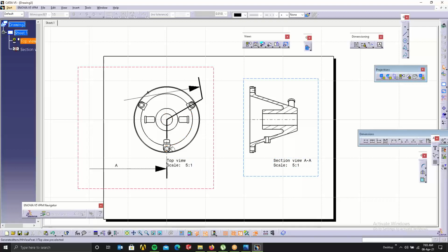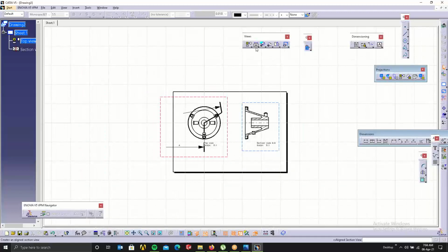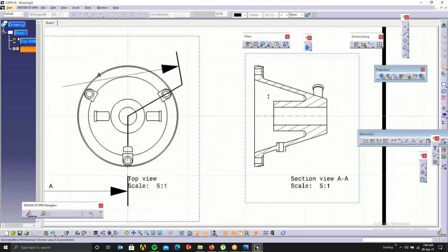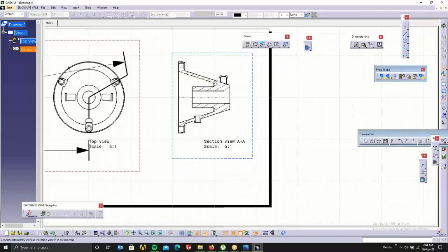Wherever you have two holes like this, take a section curve like this. So you can create sections using this. Then there will be certain details. Details means very small objects. So what happens is, see, so many values you have to give. So everything will become cramped. So here we have something called detail view. In views only it's there, detail view.